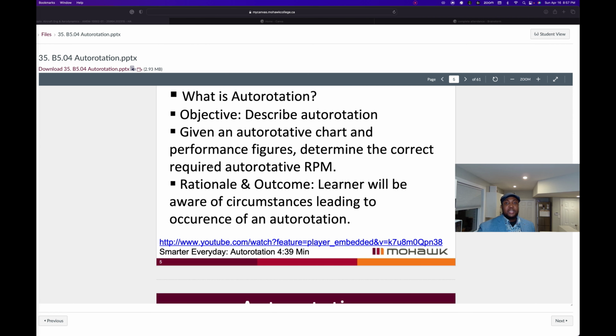An intermediate or average airspeed will allow for minimum descent rate. So it's important to not have excessive airspeed or insufficient airspeed. Just having an average or intermediate airspeed is the best case scenario for producing a very low descent rate, which is a desirable feature. Airspeeds above the intermediate will cause a higher rate of descent as well.